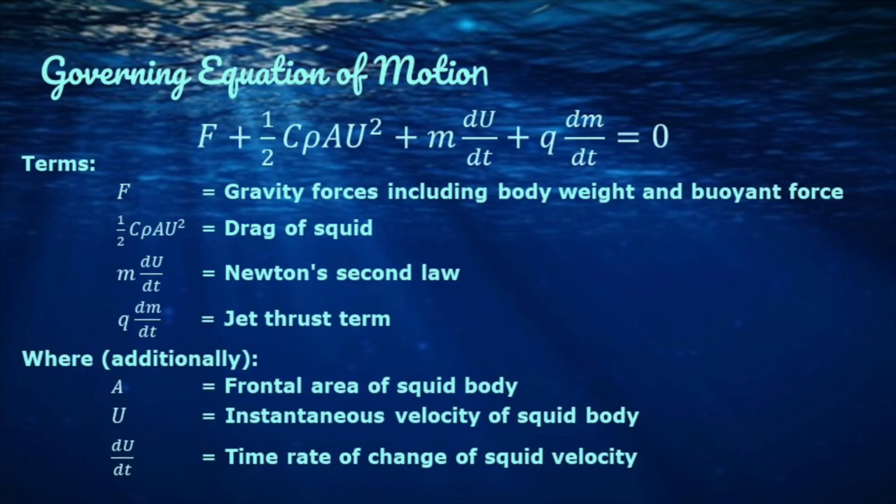Taking the equation for thrust into account, we can add this term to the general motion equation. In the end, the terms add up to the other terms of the general equation of motion. The first term contains the gravity forces. This term has the downward force of gravity and the upward buoyancy force. In the case that height does not change, this term cancels out as the upward force is equal to the downwards force. The second term is a drag force term.